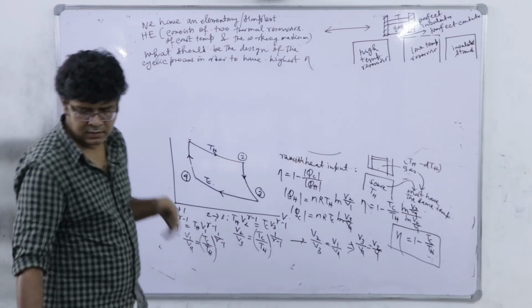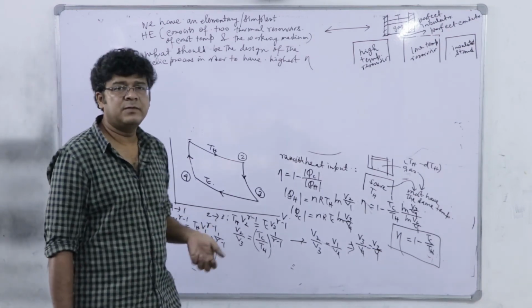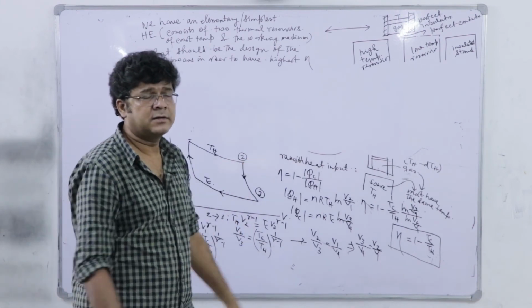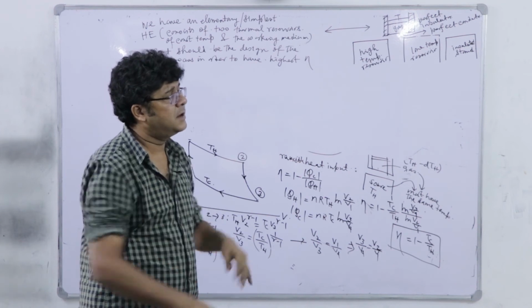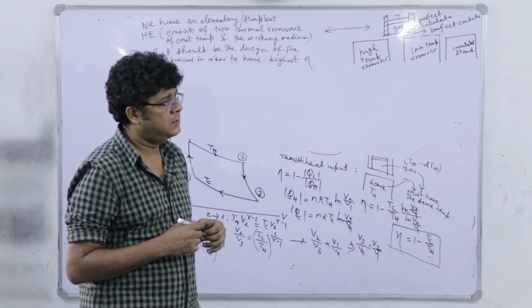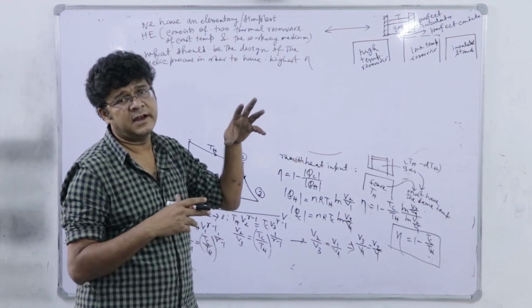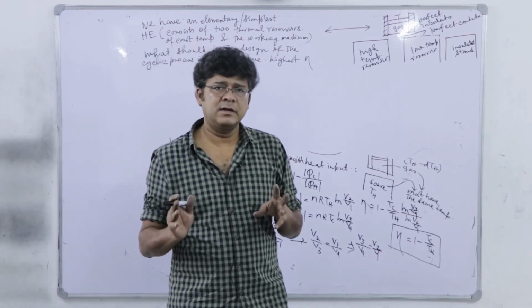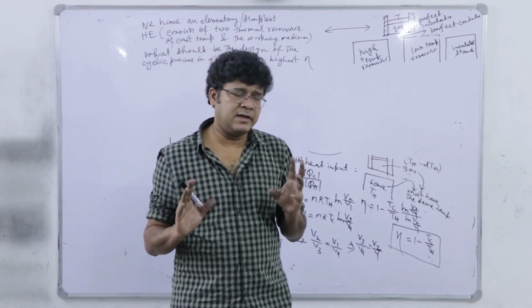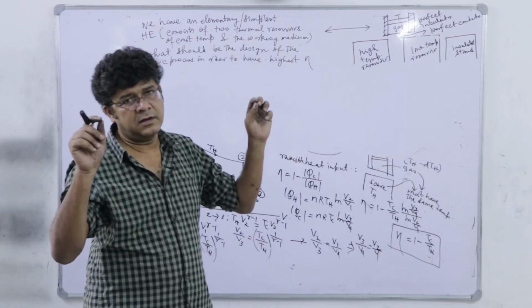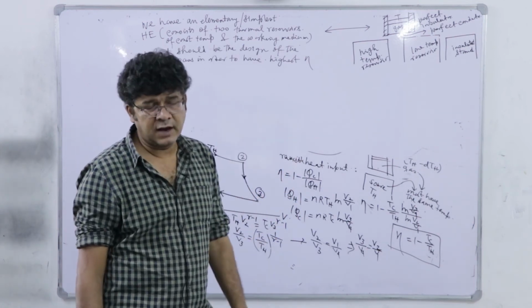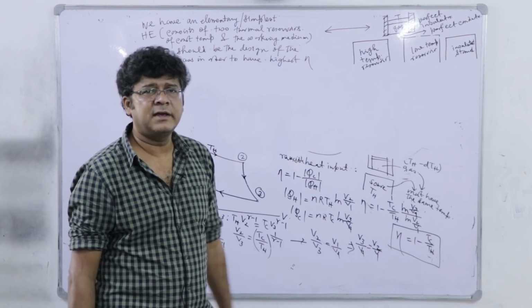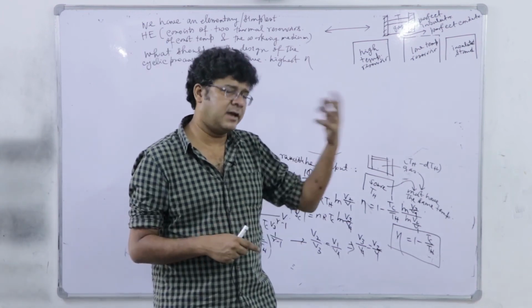See this power generation, we practice it in thermal power stations majorly on a large scale, right. And there we have the working material as water, which changes its state to superheated steam, then it expands in a turbine, and then there is a condenser and all, right. So theoretically at least, we can implement the steps of this isothermal heat input, though it is not at all theoretically feasible, then adiabatic expansion, then isothermal heat rejection and adiabatic compression.